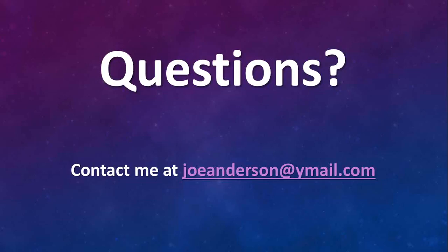All right. Let's see. I promise that someone is asking this. Have you found that UE Systems spreadsheet to be fairly accurate in predicting cost savings and reduced energy consumption? It's close. It depends on if you're pulling your air leak data right, if you have the cone far enough away from the leak. You should be about 15 inches away from the leak to get an accurate recording. If you're right up on the leak, it's going to give you a higher decibel reading and falsify your information. So the goal is to understand the tool and how to use it properly, making sure that you're about 15 inches away from the leak.